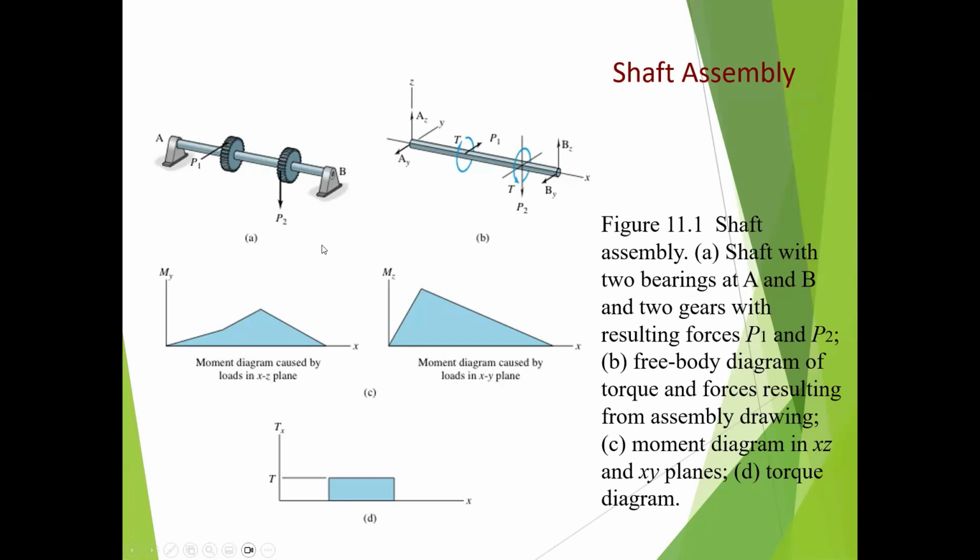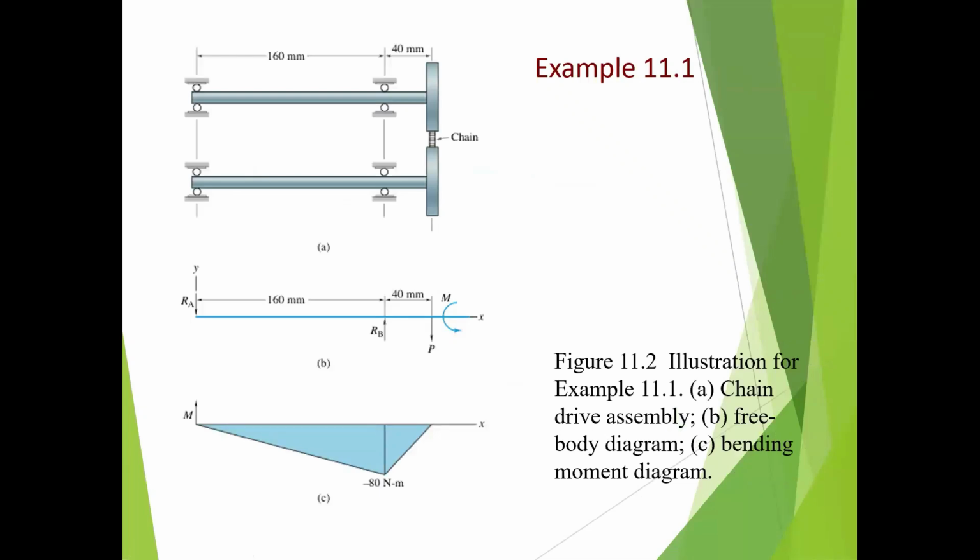That means if you get lost, come back and check your free body diagram. If, no matter how you try, the answers are ridiculous, come back and check the free body diagram. Usually the free body diagram causes the bigger trouble. So this is an example.